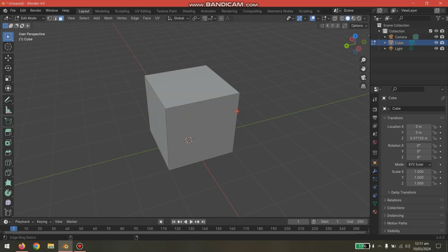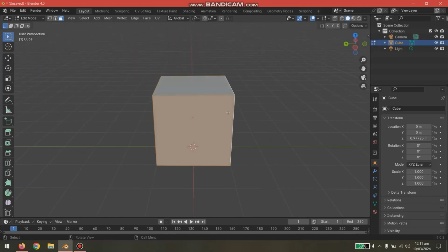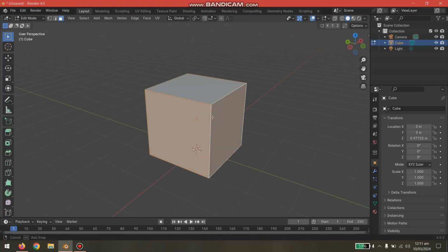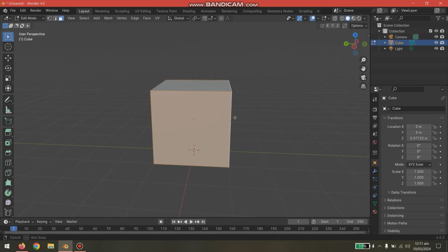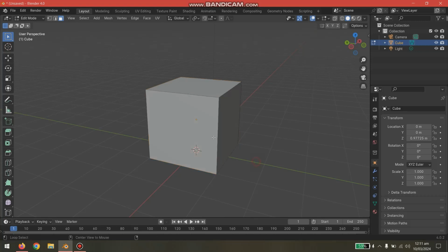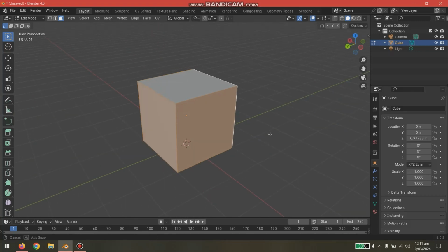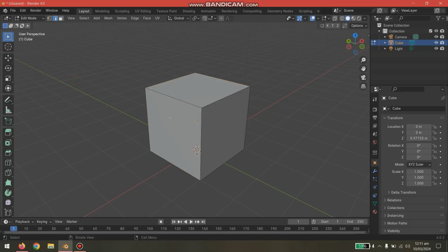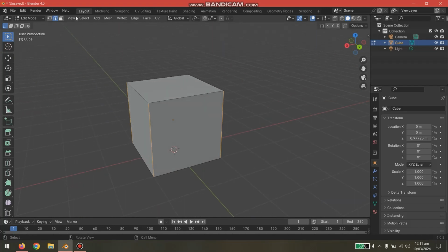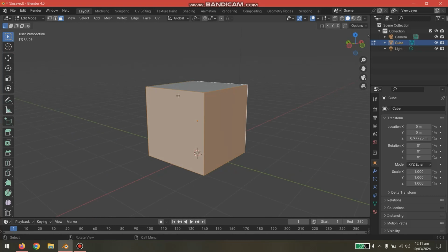So I'm gonna select the sides because this is a building and we want windows on all sides. Okay, not the top one because we will extend another floor here. So just select these by pressing Control Alt and selecting a side. If you press just Alt, it will also work, but it all depends on how you use it. So if I'm on edges and I press Alt click, it won't work. But if I click Control Alt, it will select all vertices, or edges you can say, depending on your selection. Alt is fine for faces, but Control Alt for vertices and edges.